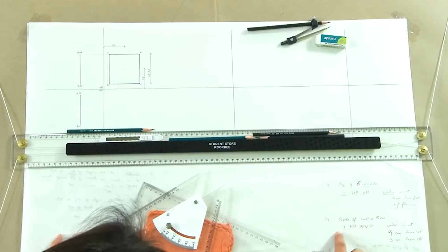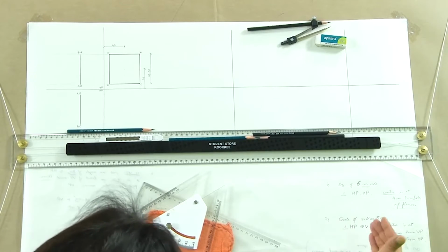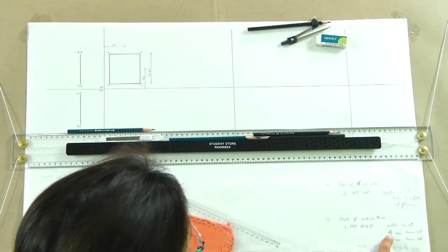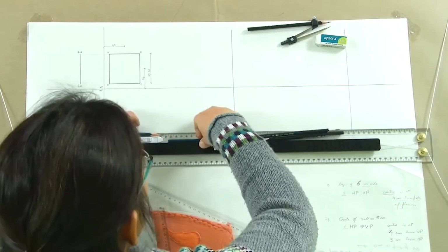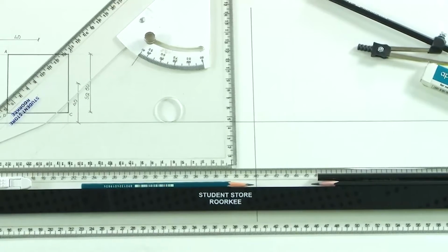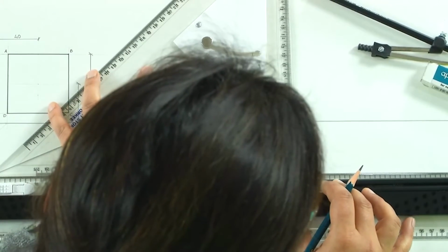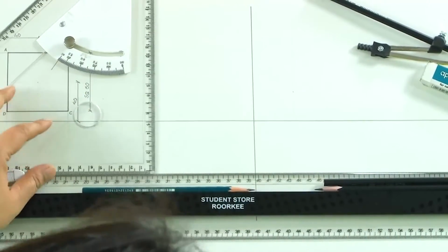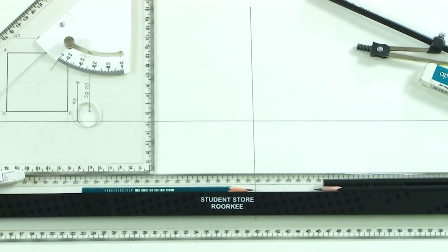What we have to do? We have to draw the true projection. Since it is perpendicular to both HP and VP, it implies that it is going to be parallel to the side plane. So, we will start with drawing or locating the center in the side plane. So, the center is at 4 centimeter from VP. So, we will mark 4 centimeter from VP. So, the center is going to lie on this line, and 3 centimeter from HP. So, which means 3 centimeter above HP is the center of the circle.